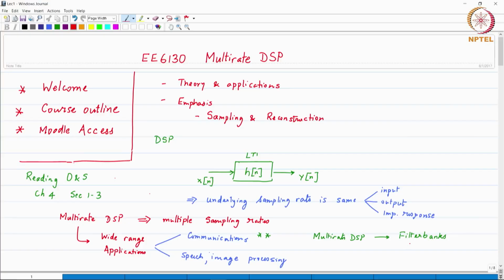It turns out that filter banks are a framework for us to understand OFDM, orthogonal frequency division multiplexing. This is a waveform that you see a lot in the 4G and the 5G cellular standards. Of course, there is a communications viewpoint that OFDM is nothing but multi-tone transmission.